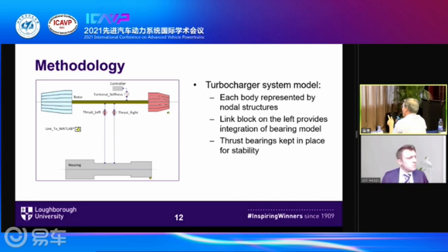So you do think the mass, the weight of your rotor doesn't matter anymore in your model? I'm unsure, as this was purely just a radial study. Okay, so in rotor dynamics, actually the weight of your rotor is a very important factor.